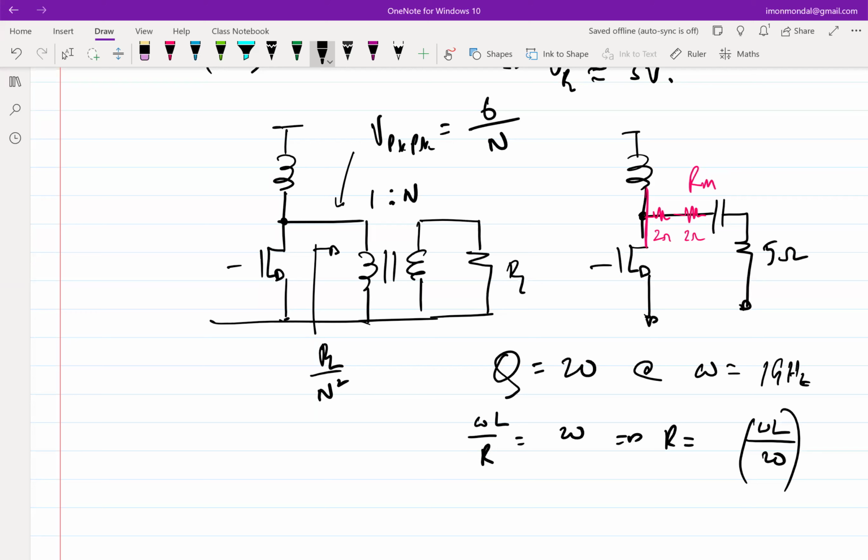The trade-off is you end up having a lot of board area, right? If you don't put anything on the chip, you have to put it on the board, right? If you go to our lab and see how a compact board looks like with respect to something which is not very compact, and debugging things on a board is another headache. And the board area directly affects the area of the technology it is going in.